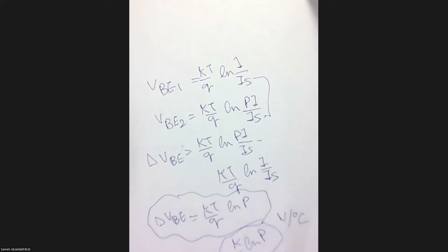So this can attribute to the equation somehow, and we will examine this in the next step as well. A third and an important point here: whenever you do any measurements, you have to have what we can call a calibration or a reference. I mean, you have to have a signal that gives you a reference concerning the voltage you are measuring.